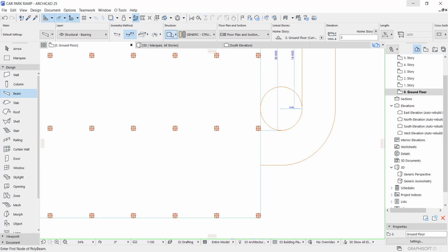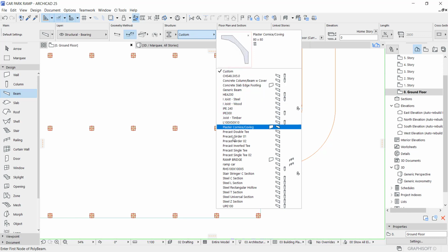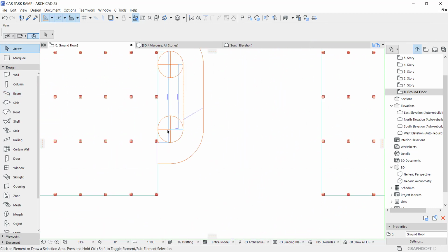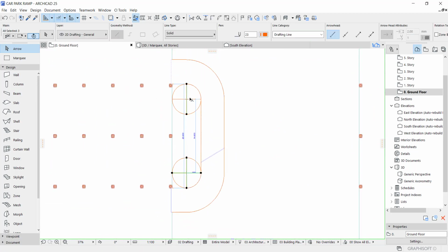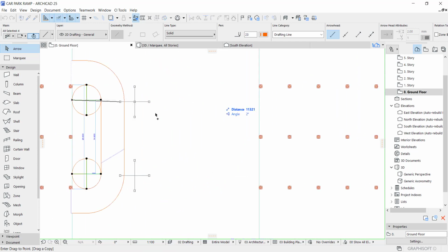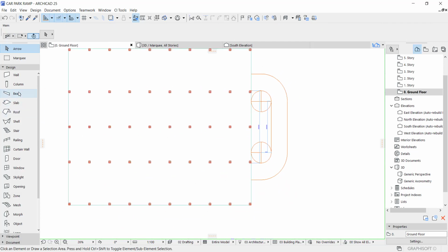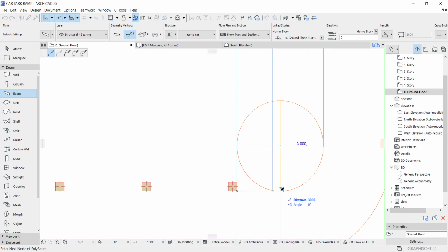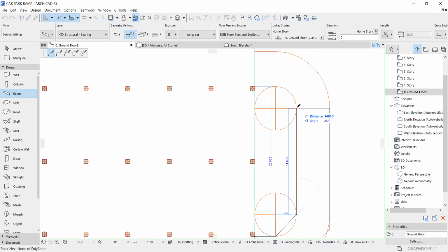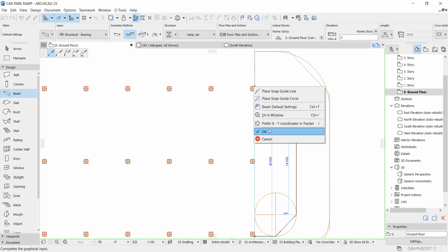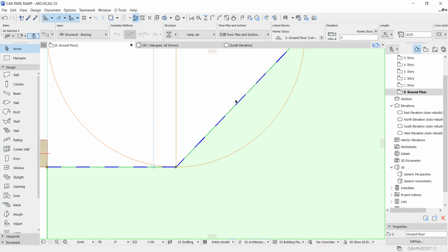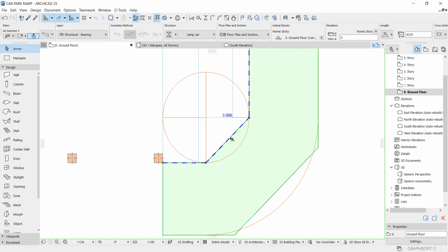Let's use a continuous beam and you change it to complex beam. This is it. Here you pick it. Then we go to custom and we look for that profile we created. And then all you need to do is take this point, this point actually helped us, so we can use it as our reference. So go to your beam, select the continuous, make sure all this is activated and you start like so. It's pretty easy, right? All you need to do now is make this editable. It is grouped. Suspend the group so you can edit.